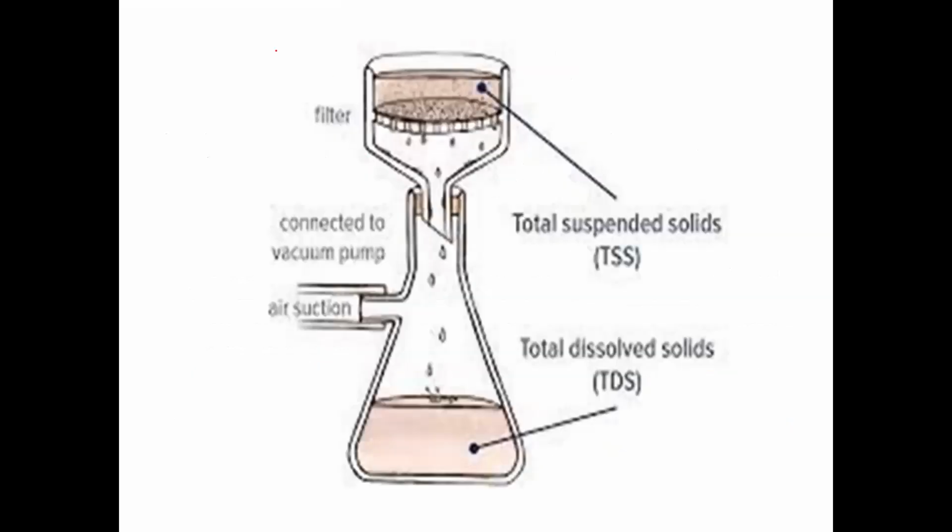Again, what remains on the filter are your total suspended solids. And the clear water that we think is safe also contains dissolved solids. When you boil it, you see the solids, which could be salt crystals, other particles, or minerals in it. So those are your dissolved solids.